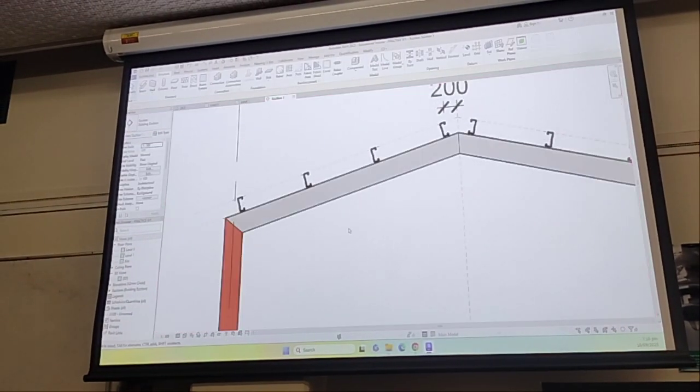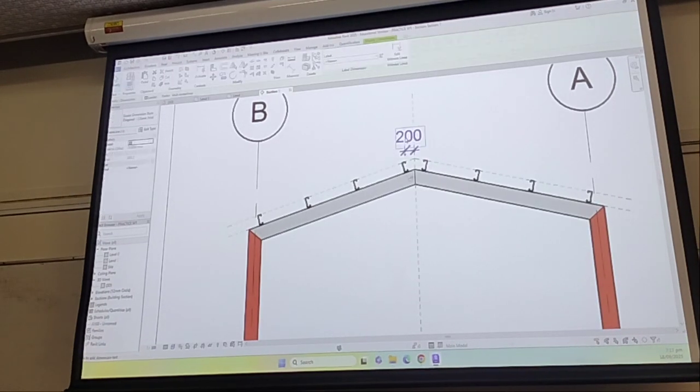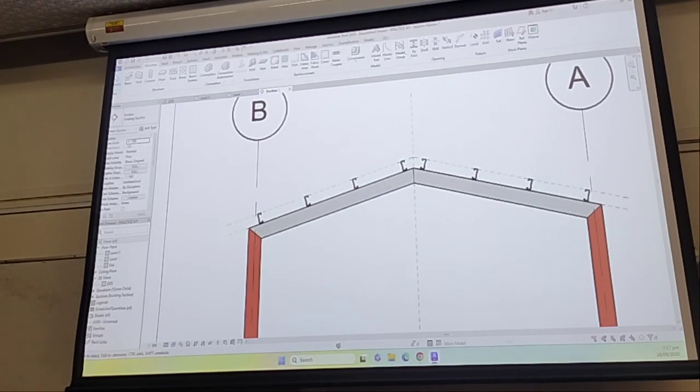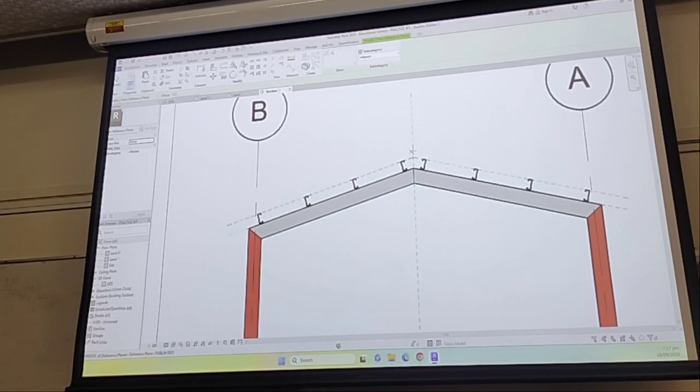Alright. So I'll unhide those. Have this one, or make another reference plane. This is just one of the different ways you can do it. Alright, there's many different ways you can do it. Parallel. I see that parallel snap. And then name this one P-cleat reference.